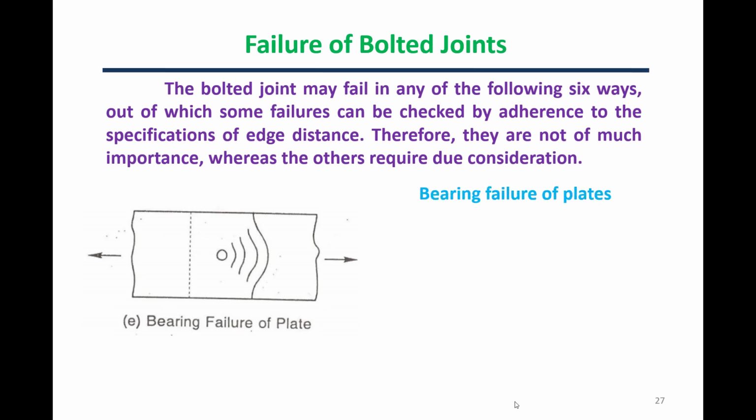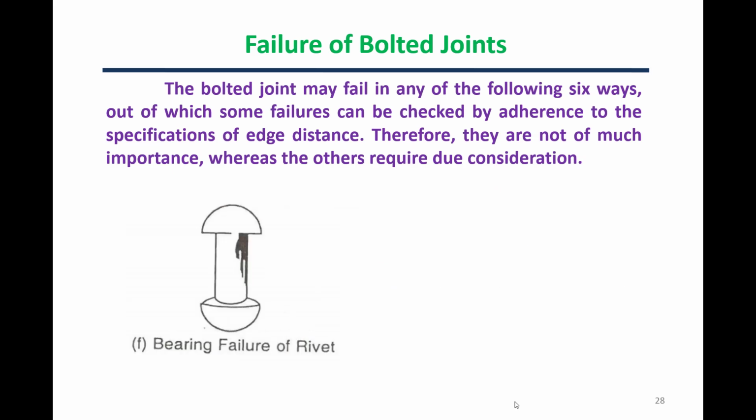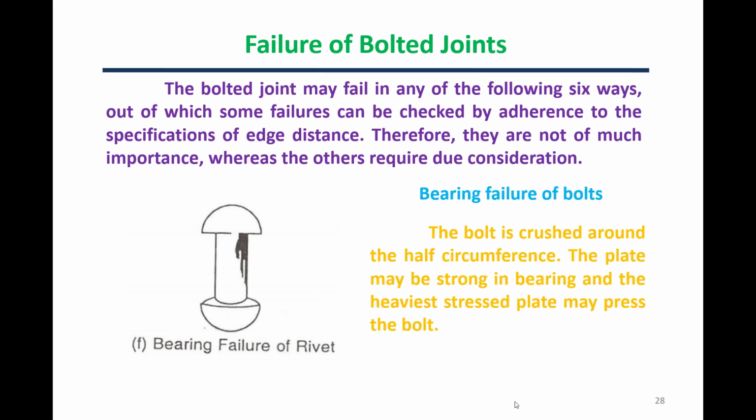Bearing failure of plates: the plate may be crushed when the bearing stress in the plate exceeds the working bearing stress. Lastly, we have the bearing failure of bolts. The bolt is crushed around half of its circumference. The plate may be strong in bearing, and the heavily stressed plate may press the bolt.